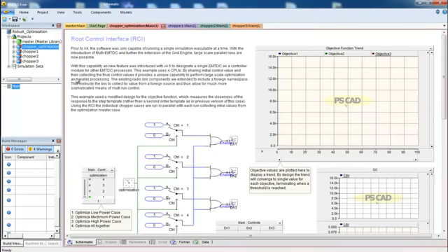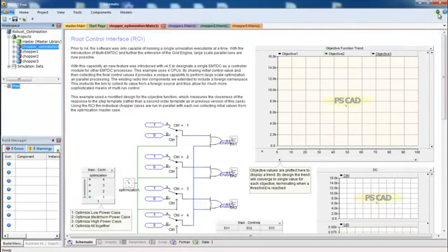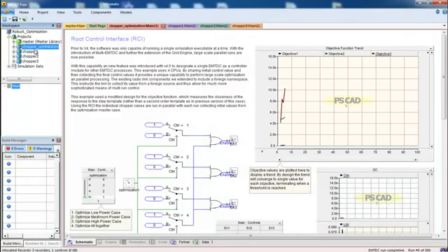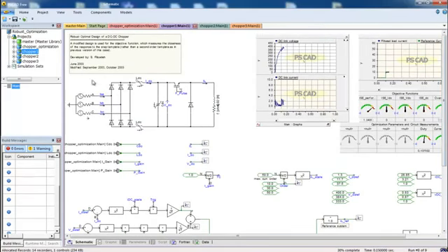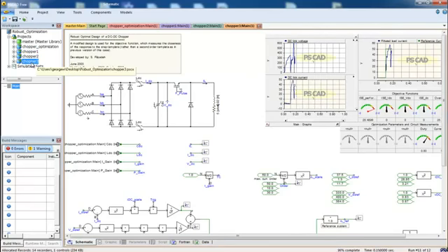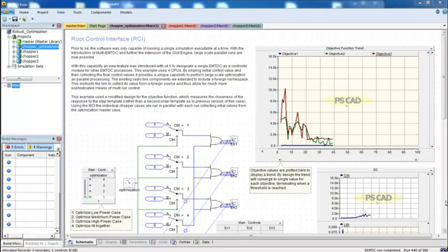Let's run it and see what happens. Here in the master project, you can see the objective values coming from each slave. In each chopper slave, you can see the output of the circuit for that power level. The output changes for each run as new tuning parameters come from the master. Back in the master project, the objective values from the slaves approach a tolerance level of 0.01.